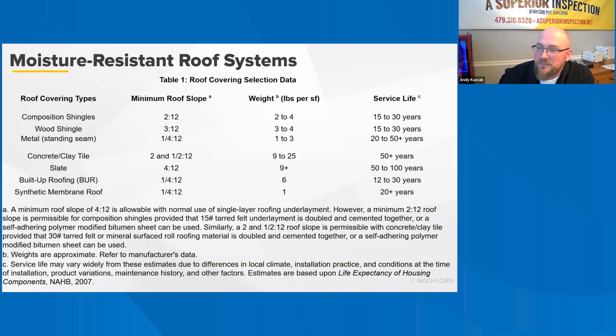A 19-inch strip of underlayment felt should be applied parallel to and starting at the eaves and fastened sufficiently to hold in place. Starting at the eaves, 36-inch wide sheets of underlayment should be applied, overlapping successive sheets at 19 inches and fastened sufficiently to hold in place. Generally, you're not going to see that information, but this is just information for you to be aware of.